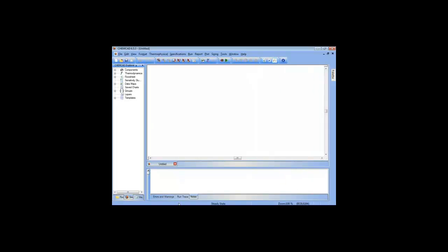The status bar is down here. We convey information about ChemCAD down along this bottom as well. Right now we are in steady state mode. If we were in dynamics mode, that would change, and you would have the time that dynamics is running in. In a second, when we get into doing a simulation, you will have your thermodynamic information down here.